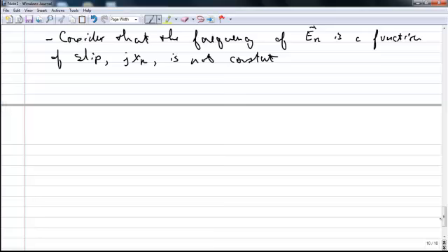So the situation now is that we have a three-phase voltage applied to the stator windings of an induction motor, and this induces a voltage on the rotor. And in general, the greater the relative motion between the rotor and the stator, the greater the resulting rotor voltage and frequency. The largest relative motion occurs in the situation we talked about before, where the rotor is stationary.